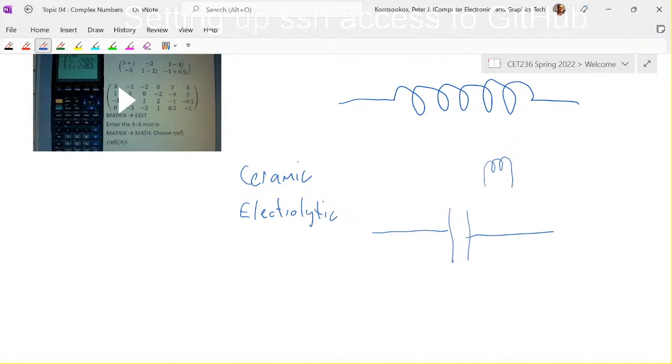Yeah, right. So see there's a cross on the top? Have a look, there's a cross on the top of the... That's because if you treat electrolytic capacitors incorrectly, they will explode. Right? And the cross is etched onto the top of the capacitor, so we know what direction they're going to explode in. Okay? Now, it's relatively difficult to get them to explode.